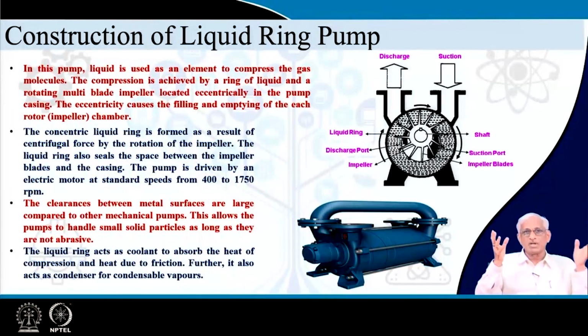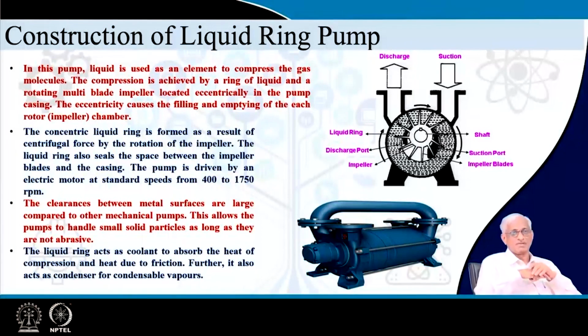And the liquid ring also acts like absorbing the heat of compression and heat due to friction, if any. It also acts as a condenser for condensable vapors at that local temperature, when the pump is working. So, there are multiple advantages with respect to the liquid ring pump.